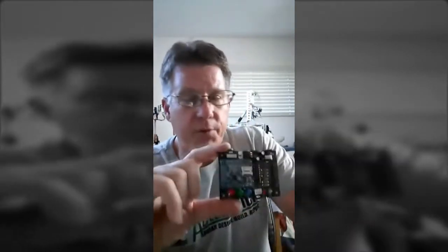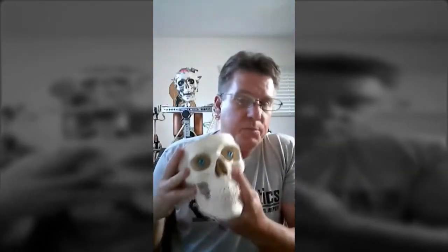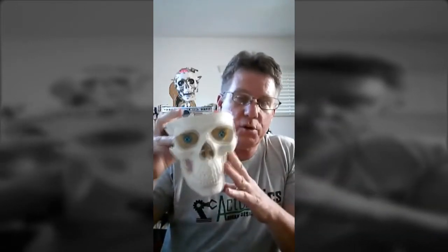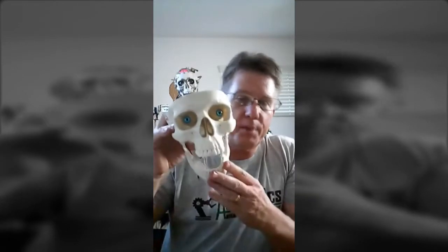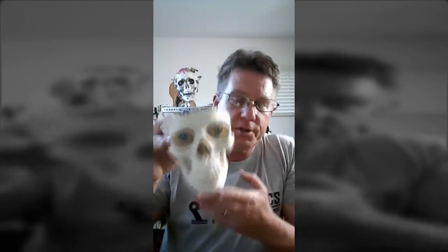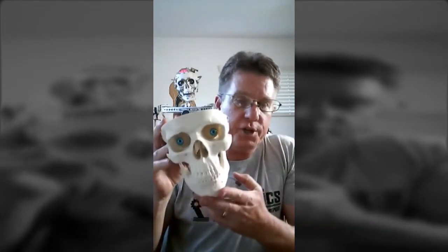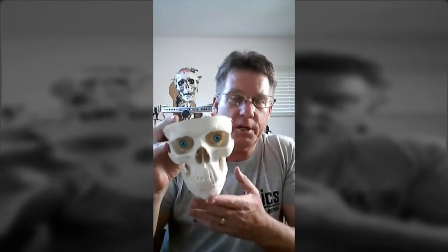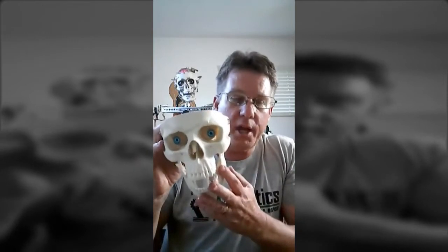One other thing with using this board, with some of our older boards that we used to use, in order to drive the servo that drove the jaw, especially if you were using an audio track that had music in the background, if you just fed that full track into the controller, it would use everything, every drum beat, every volume change, and the jaw would respond. So the way we got around doing that is we split a stereo channel. One side of the stereo channel, say the left, went to your speakers, and that's what everybody heard, and the right channel actually went into the controller.